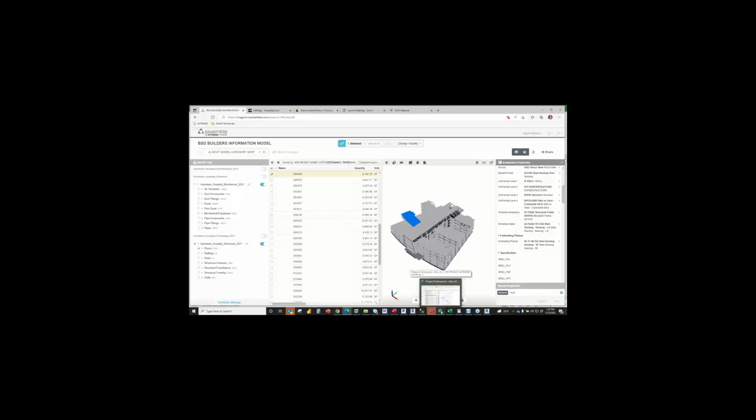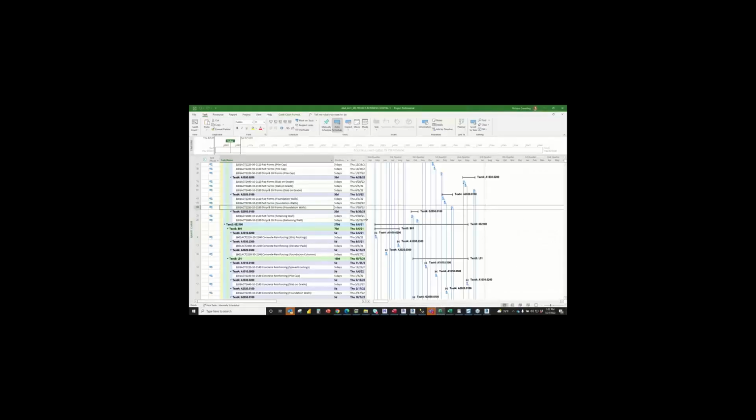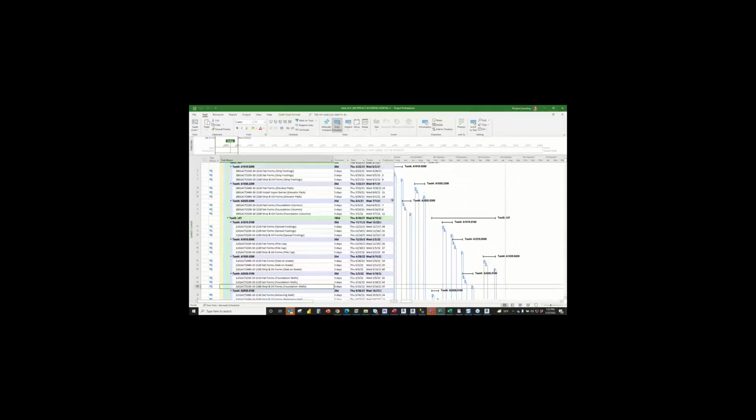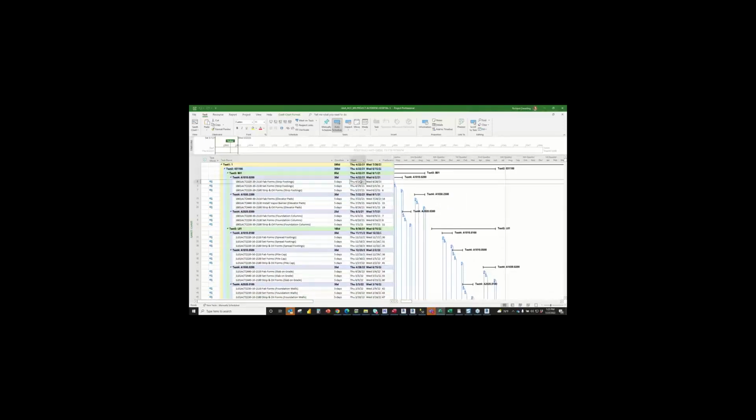Let's speak back to this schedule here, if I may. It's important for you to understand that what goes into not just Navisworks, but Synchro or other visualization applications, the logic does not come along for the ride. All that really goes in there is the dates. And the dates are like a light switch. Turns it on, it turns it green, and then when it's done, it returns to its native shading. Again, we're making frames of a movie.